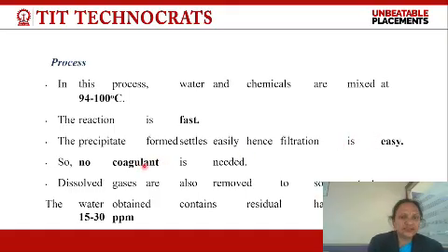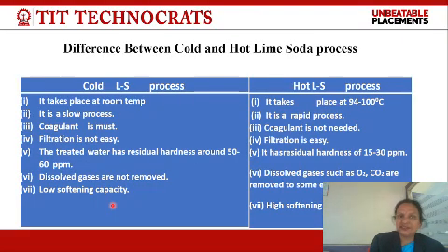No coagulant is required in this process because the reaction is already performed at hot conditions, and the residual hardness is 15 to 30 ppm. It is a point to be noted that the residual hardness of the cold lime soda process was 50 to 60 ppm, and in the hot lime soda process it is 15 to 30.